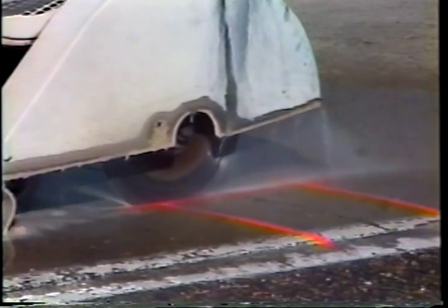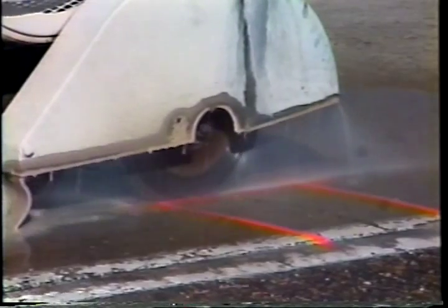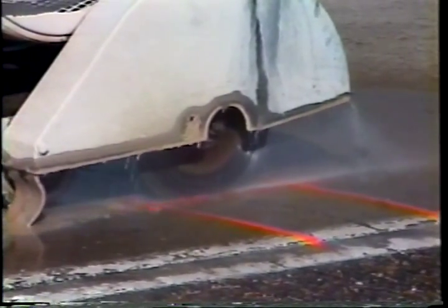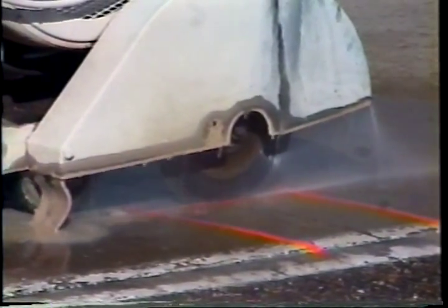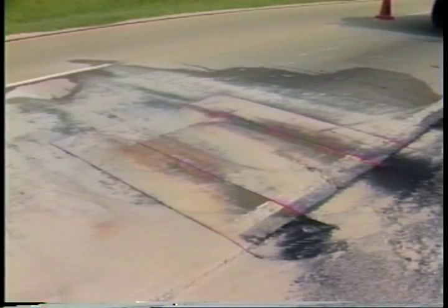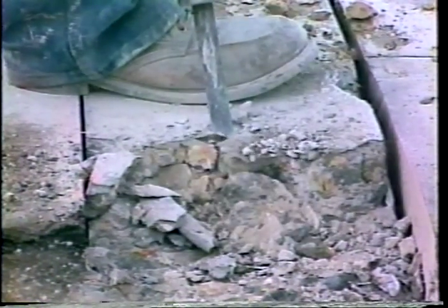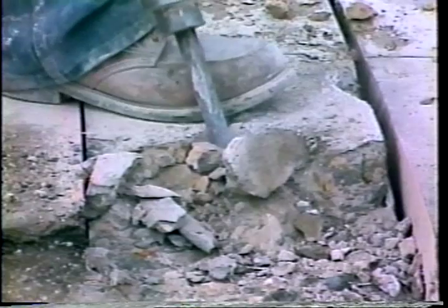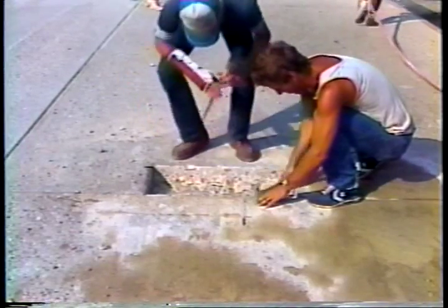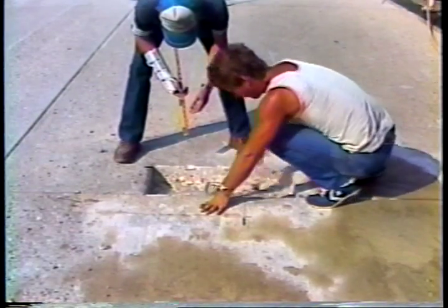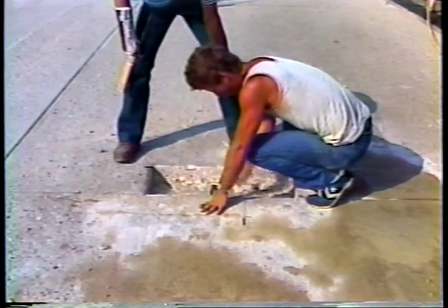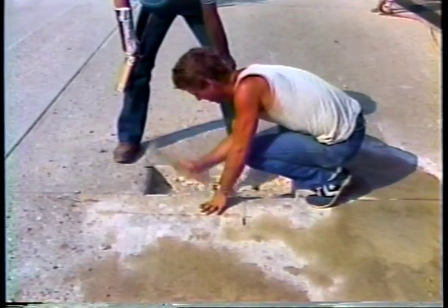When the saw cutting and chipping method is used, the first step is to make a vertical saw cut about 1 to 2 inches deep along each mark. For large repairs, additional saw cuts may be made within the perimeter to speed up the chipping process. Chipping should start at the center and progress toward the boundaries. Periodically, the bottom of the repair should be sounded to ensure that all deteriorated concrete is removed.